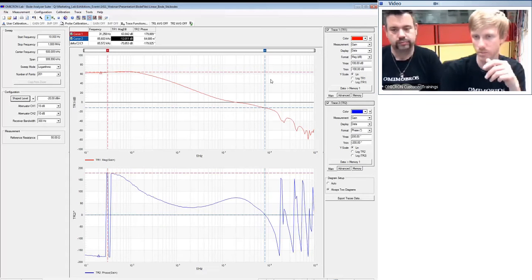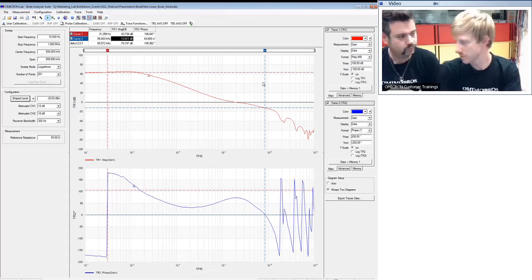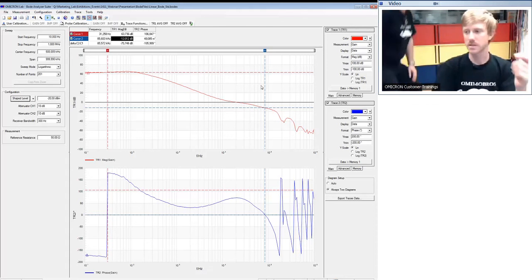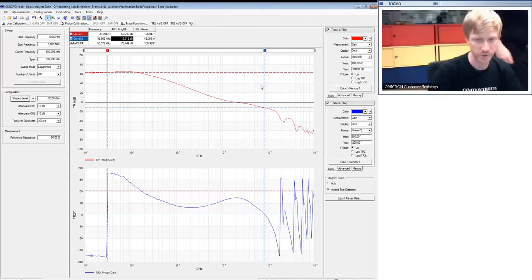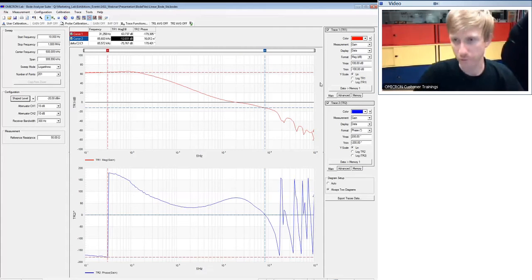Okay, perfect. So now we can probably change the output current. Absolutely, the load current. Because this is something we mentioned before. You have to measure your system under all load conditions that are bad for your system. So we now store this curve into the memory to be able to compare it to the result we will see afterwards, to check if something changes.